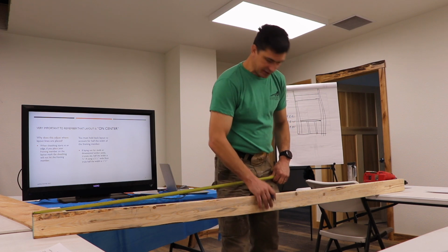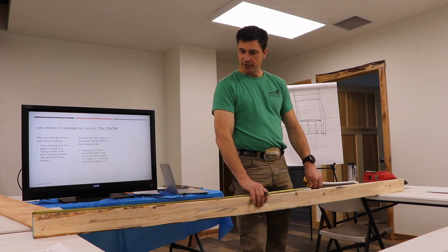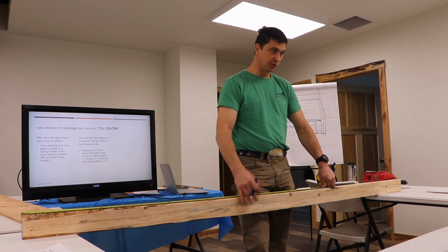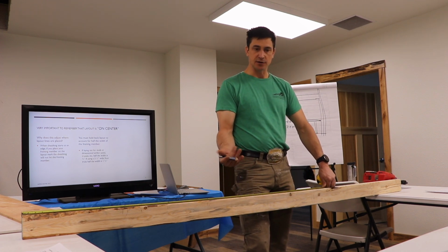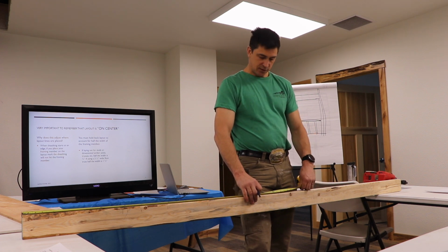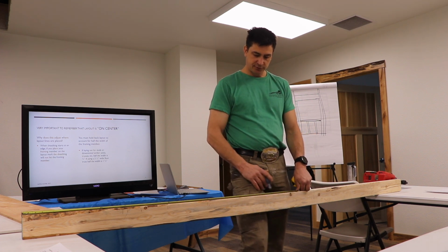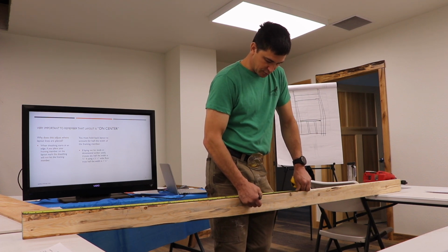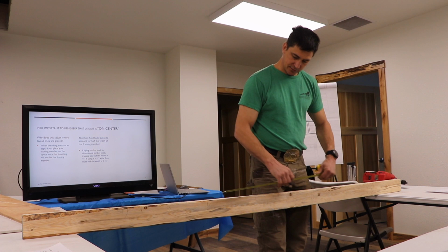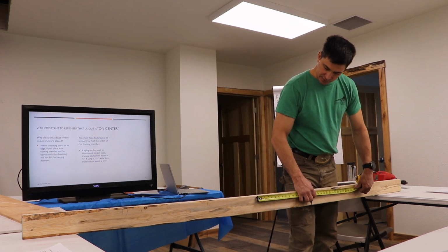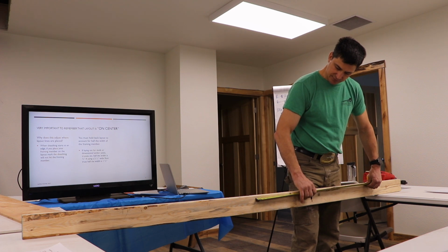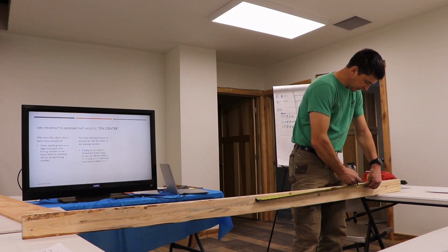Before I do my layout, I'll take my plate, and the plan will give you a dimension in feet and inches. So we've got to be 3'6.5" to the edge of the window. We'll put a mark there. Then you look at your window plan and it says the rough opening is 32 7/8, so you mark 32 7/8.